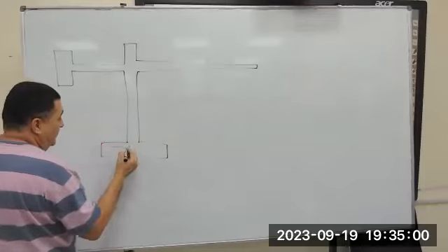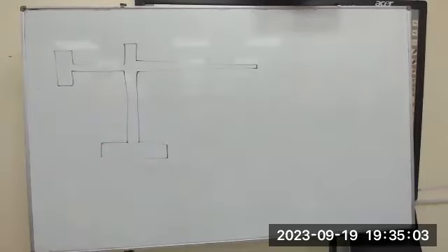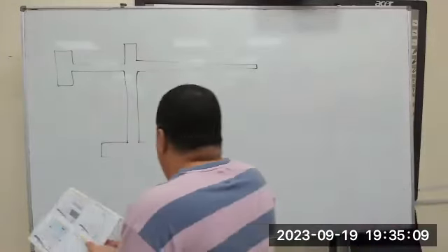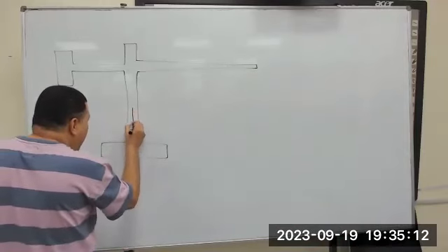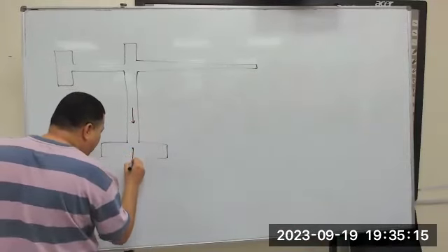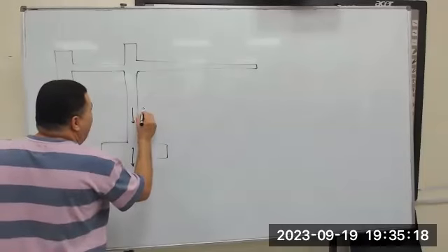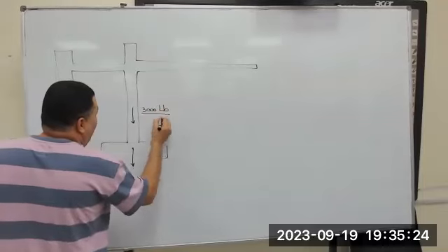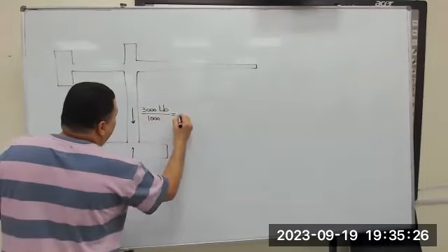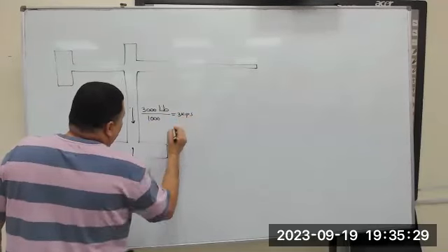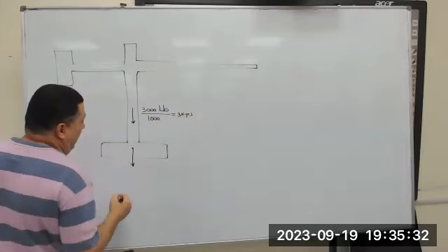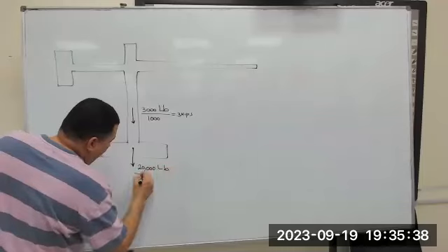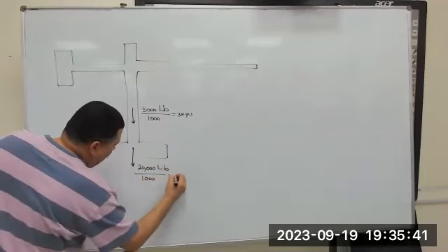Foundation is what? Foundation is 6 foot. The weight of the foundation is what? The foundation is 20, and the tower crane itself is 3. And now we have 3,000 pound divided by 1,000, you have 3 kips. 3 kilo pound, and we have here 20,000 divided by 1,000 equal 20 kips,